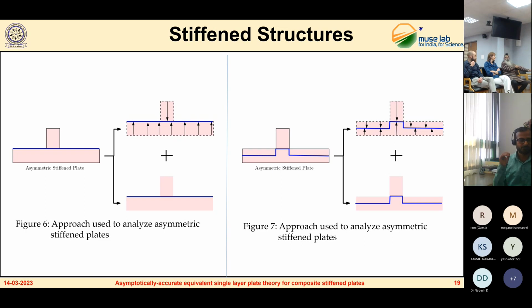Okay, sir. You have to be very careful about the continuity over there. But the other thing is in terms of these stiffeners: just to demonstrate your case, you've taken a very simple cross-section geometry of the stringer. But for the typical hat stiffeners or many other combinations like the Z stringer, you have to think about what approaches you have when part of it is not in contact with the plate, but bending and having a different geometry. So have you given any thoughts towards that?